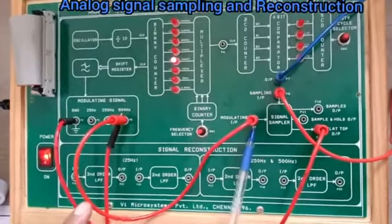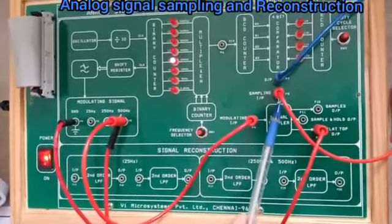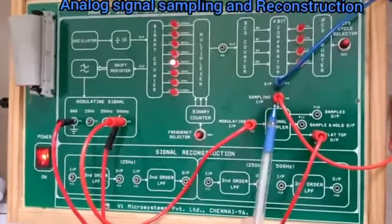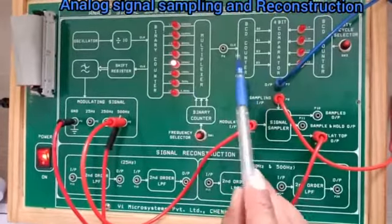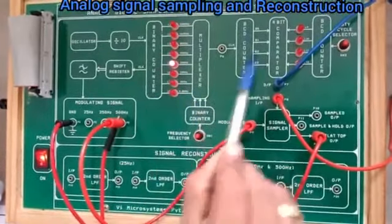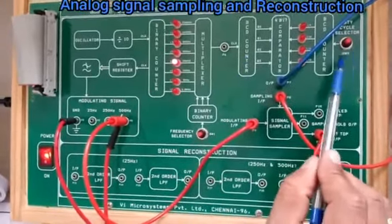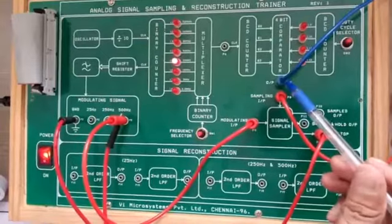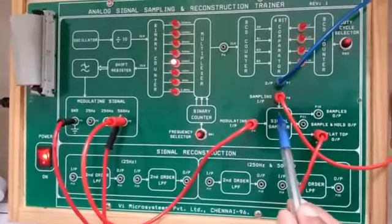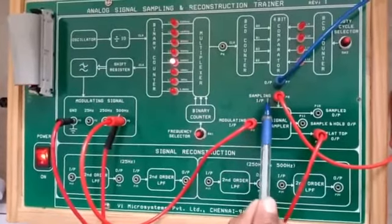At this pin you connect the modulating input. We have one more provision, that is the sampling input. For this sampling input, we need to generate a train of sampling pulses. For that we have different circuits: binary counter, multiplexer, BCD counter. Finally, from the comparator you get the sampling pulse output, and this sampling pulse output is applied to the input of the signal sampler.